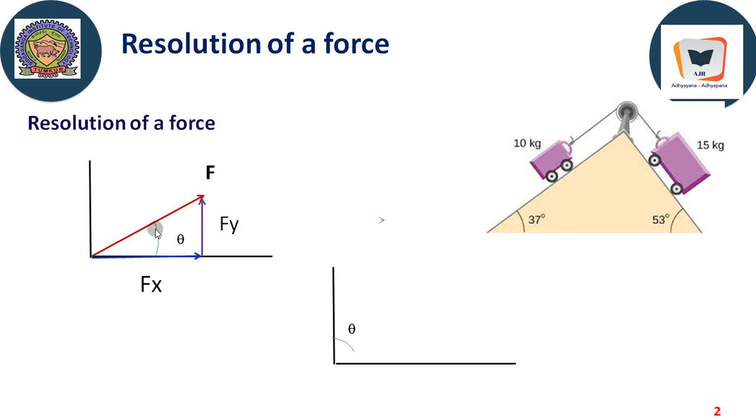We will cut this force to scale, something like, let us say, 1 centimeter equal to 10 kilonewton. Therefore, we can cut this particular force to a scale, and we will project horizontally to find the horizontal component and the vertical component. The horizontal component of the inclined force is responsible for the movement or disturbance along the horizontal direction, and the vertical component is responsible for the movement of this small trolley in the vertical direction.